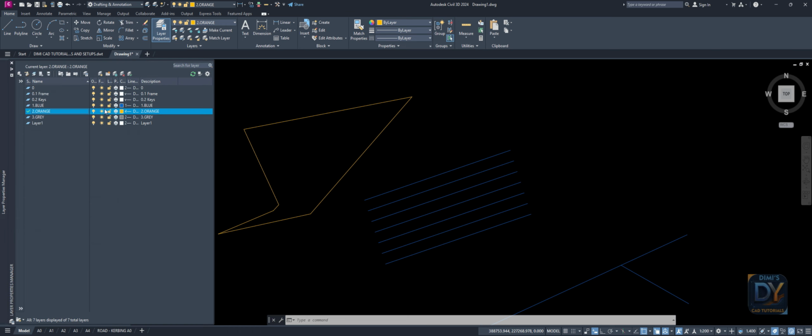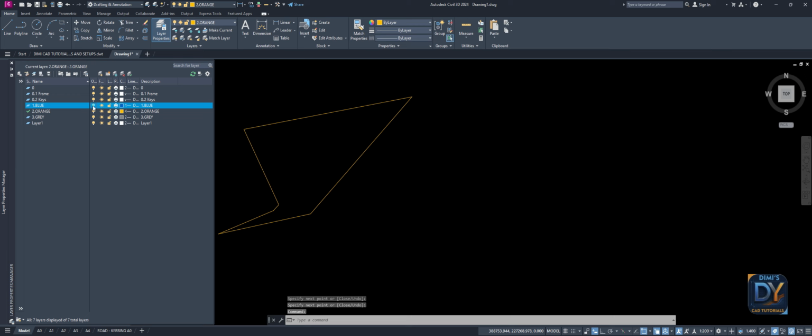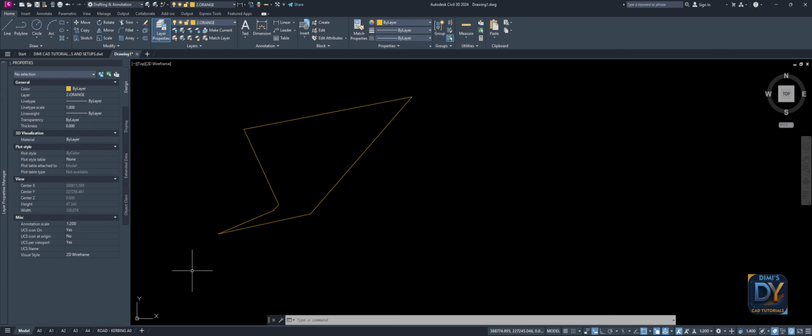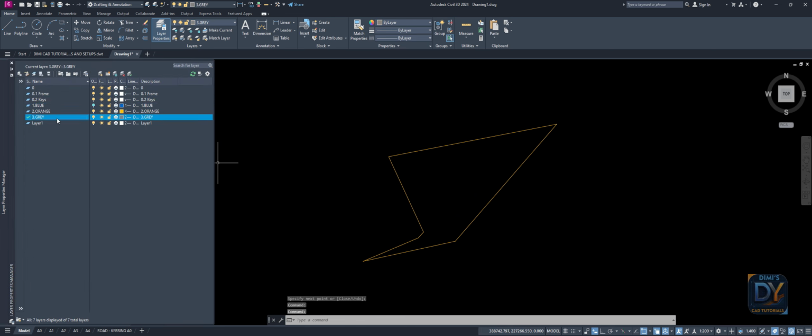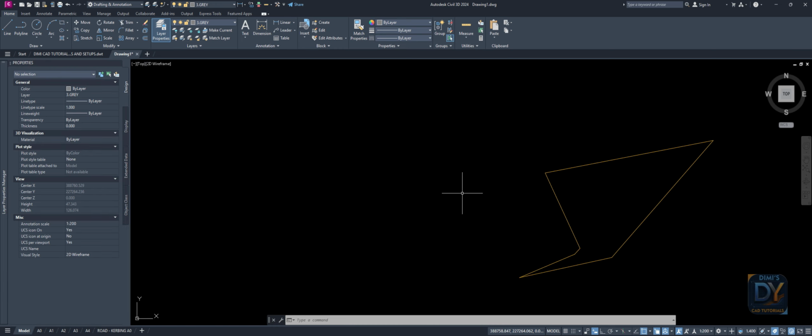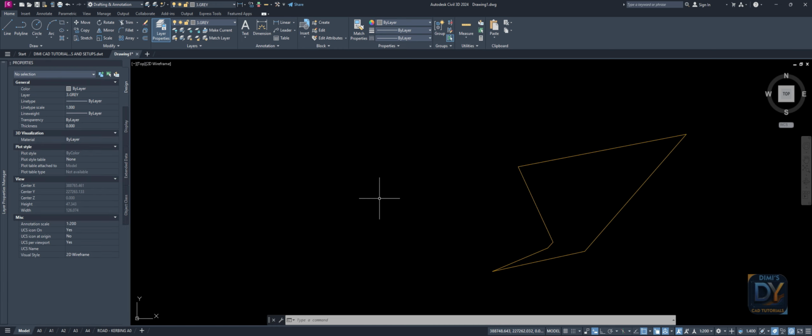Layers are really good for segregating your information. So I've got, for example, my lines on a blue layer. I can switch this one off. I can leave only that concave shape just by leaving that layer on. I can switch my current layer. The current layer activates, let's call it, your canvas, or the specific layer you draw objects in.